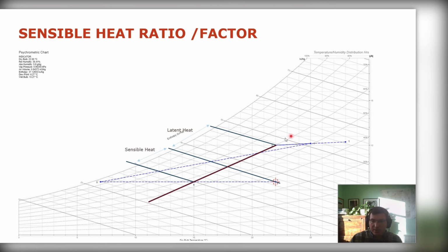So the way I would do it is, if I look between those 2 points, I draw a line vertically down to make 3 sides of a triangle like that. The line that goes straight down, the difference between those 2 points, is purely latent heat. So if I now draw lines onto my enthalpy chart, I can read out enthalpy at 0.3 versus enthalpy at this point here.